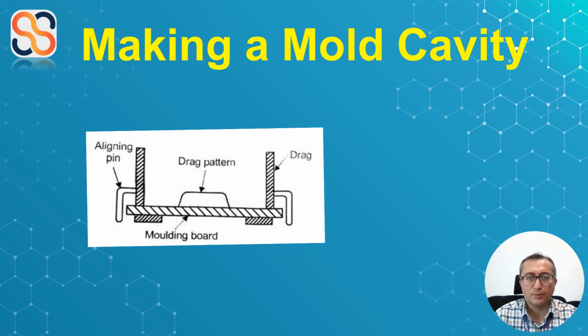Now, it is time to fill the drag with loose prepared molding sand. We need to ram the molding sand evenly around the pattern. So we fill the molding sand again and ram it down. This process should be repeated about 3 or 4 times to make sure it is packed well. Finally, we remove any excess sand using a strike-off bar to level the molding sand with the height of the molding flask. This completes the drag.